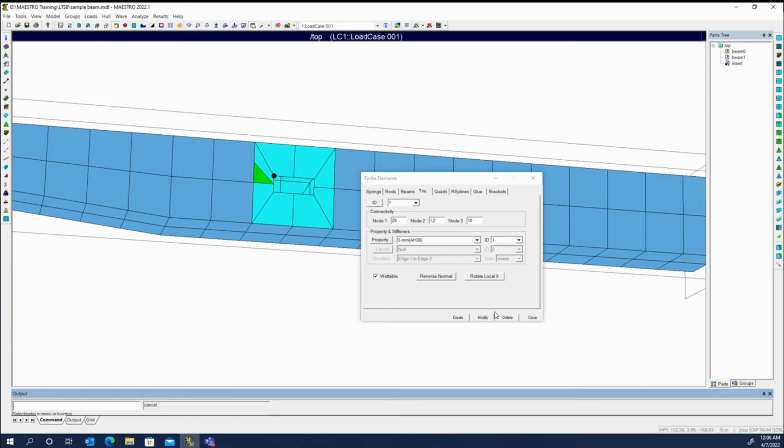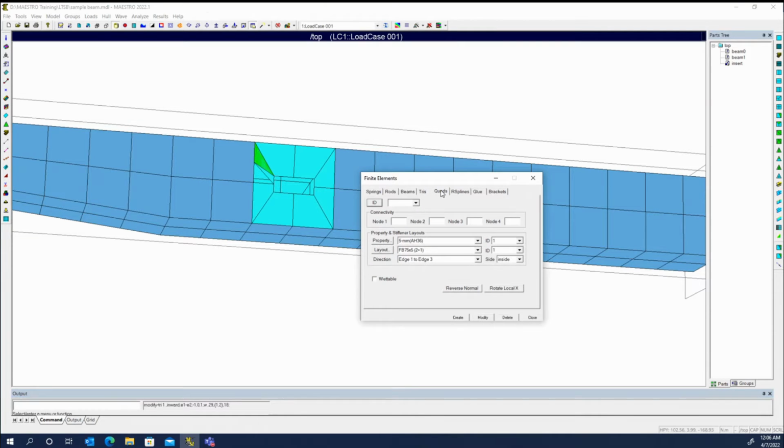And I'll just modify the nodes to go from on this side, say modify, and then I take this quad and I move nodes 1 and 2, because you could see where the arrow was to know where they started. And that's the arrangement that I wanted.